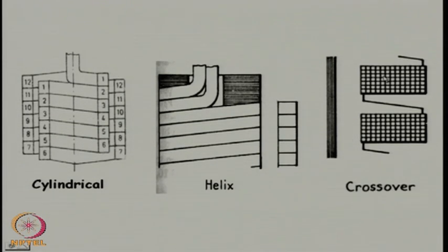The high voltage winding will usually have a large number of turns, but its current rating will be small. They can be still made up of rectangular wires or even circular wires. In the crossover winding, generally high voltage windings are divided into several groups, and the groups are wound separately and then they are connected in series to form the high voltage winding. Each group can have many number of turns and they can be arranged in multiple layers.